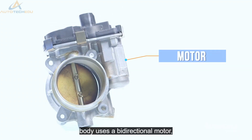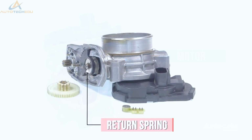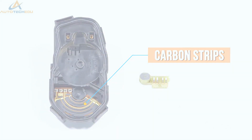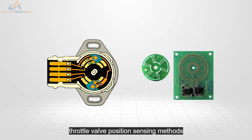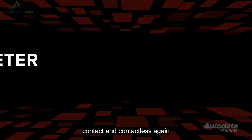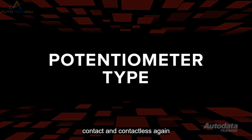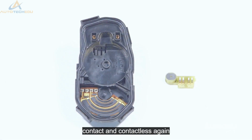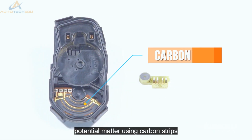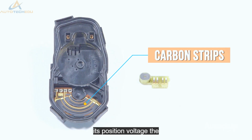This type of throttle body uses a bidirectional motor, a heavy return spring, and 2 variable resistor sensors. There are different types of throttle valve position sensing methods. Just like the APP, there is contact and contactless. Again, the contact type is a potentiometer, using carbon strips with its position voltage.